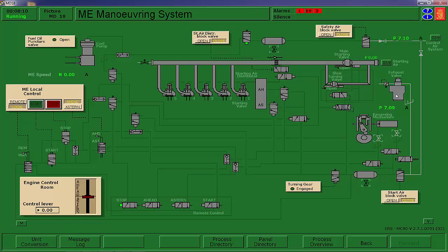The reason for that is the main engine lube oil system is the source of hydraulic fluid for your hydraulic push rods on the exhaust valves. You use a hydraulic system to open the exhaust valves in operation. Once the main oil system is pressurized, it will feed a small amount of oil into that system to displace any air, purge it, and keep it full of oil.